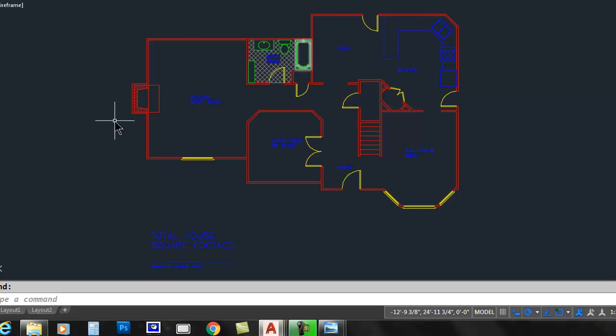Okay, so what you need to do, if you look at your assignment handout, you see the finished product at the bottom of the page, the picture of it. So you're going to need to create 3 viewports. Now, very important, for the viewports on the right, bathroom and bay window, you have to create a second layer, viewports 1, and do not make that no plot, because there are plenty of times where you want to see the viewport border. That would look very strange without that circle around the bay window viewport. And you want to just isolate the bathroom and have that with a rectangular viewport border shown.